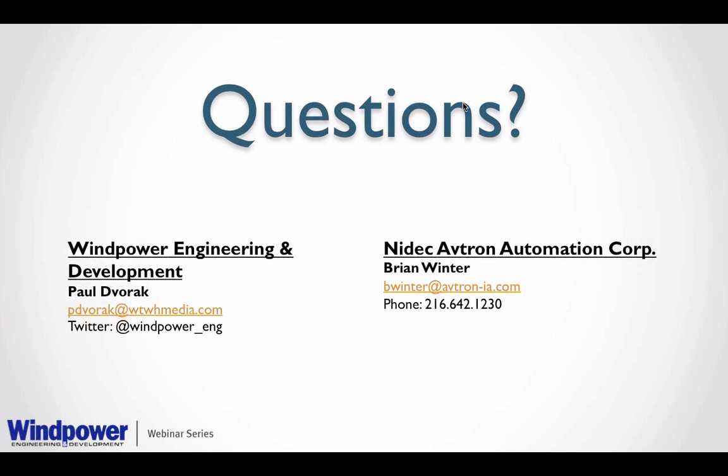Okay, Jim has a question here. Common problem we have seen on pitch motor encoders is the loss of pulse count. What aspect of an encoder can help prevent pulse loss and make the encoder more robust? Yes, that's pitch. A loss of pitch count really is, I'll call it the symptom, the overall symptom of the problem. The real problem is hidden underneath, and that is the encoder is actually failing you in one or several ways. The first thing you probably want is an encoder in there that's got some diagnostics, so it can tell you if it's healthy or not.